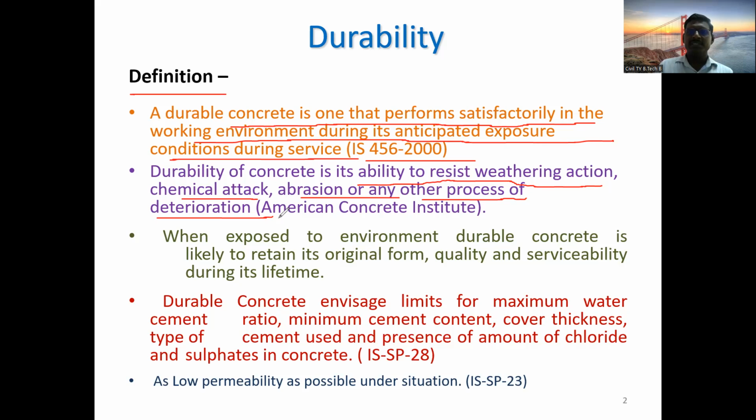If the water and cement paste come up on the surface, cracks will form. So these parameters are very important related to durability. When exposed to the environment, durable concrete is likely to retain its original form, quality, and serviceability during its lifetime.